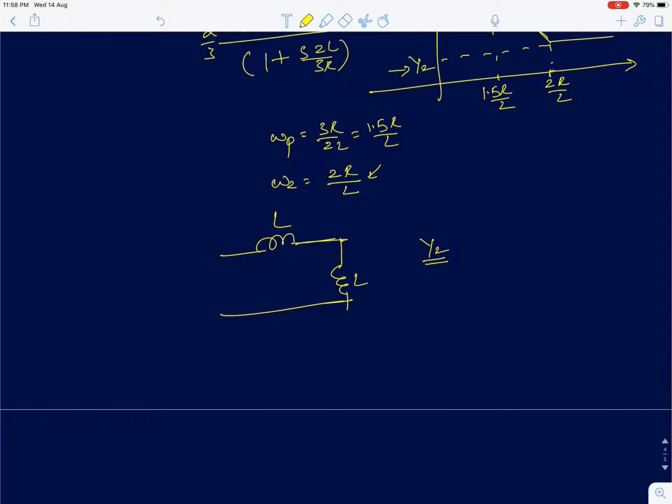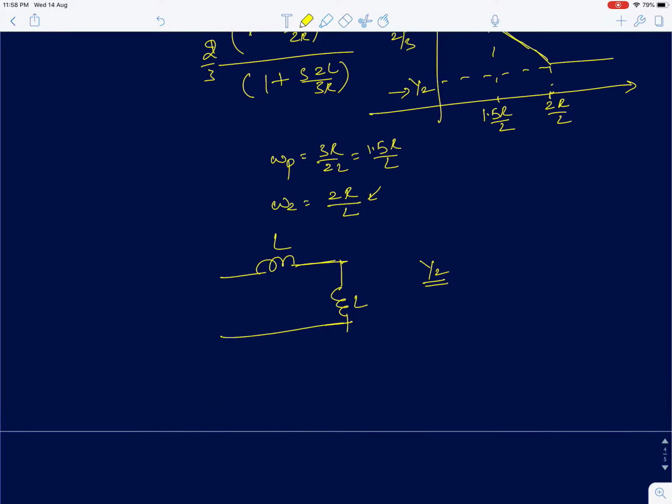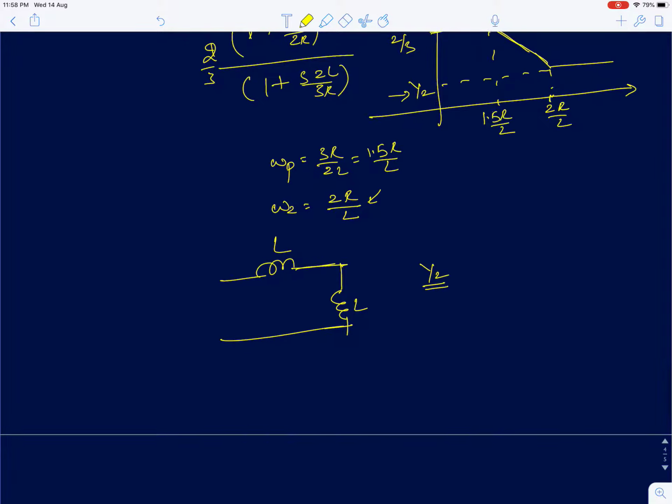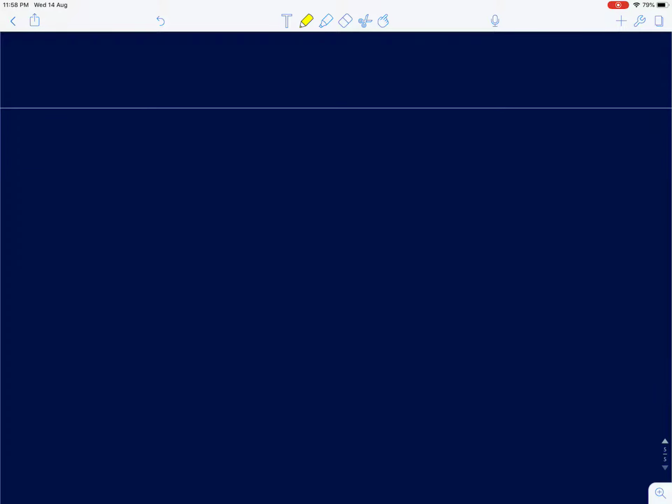So with this, we actually discussed how to find the transfer functions. I'll just take a few more examples to derive transfer functions. Now we'll do it very quickly using intuition. The DC gain for this circuit is going to be 1. This inductance will be short circuit. The output voltage is taken here. You are applying the input voltage at this point.